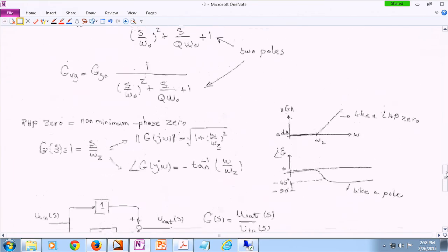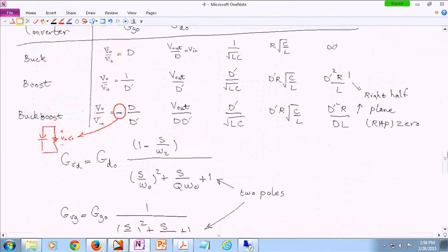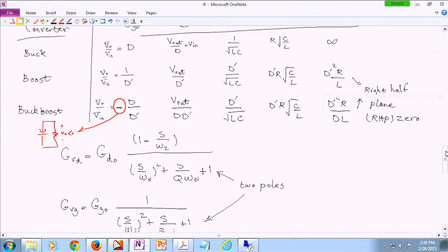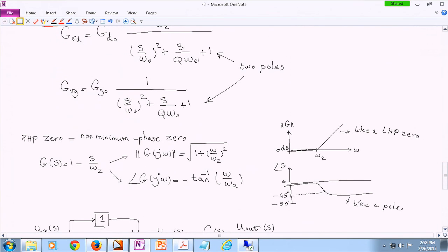Yes, if you have a perturbation in the system that is only 10 kilohertz, then for the Bode plots that we are going to have in the future, this omega z does not play a significant role, okay? Because at 10 kilohertz you are pretty much here. Your zero has not had a chance to actually create 90 degrees of delay, okay? So this is usually on the order of 1 mega, or something like that, radians per second.